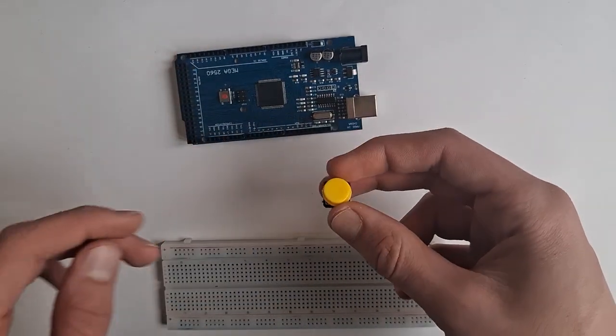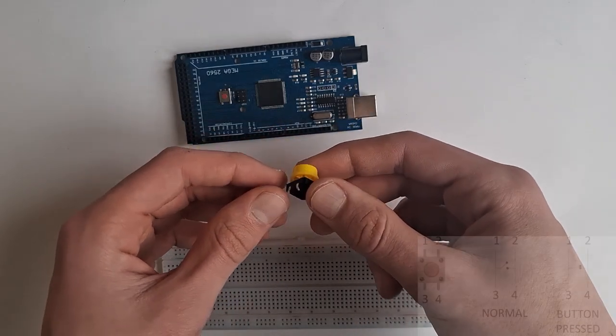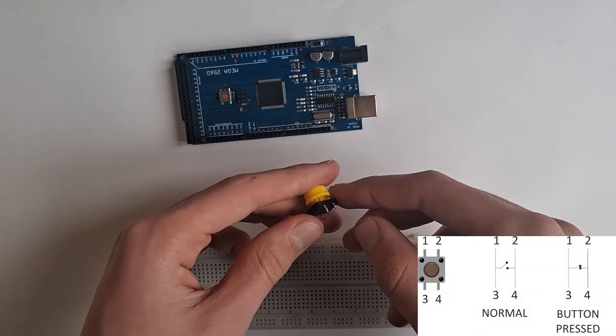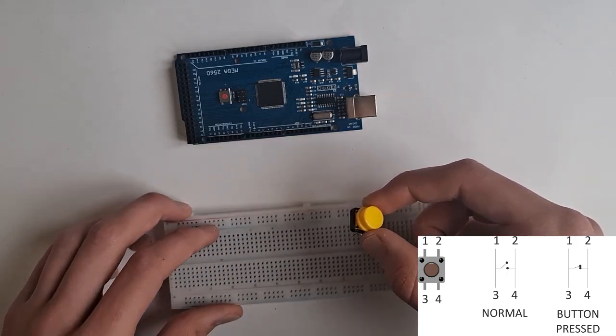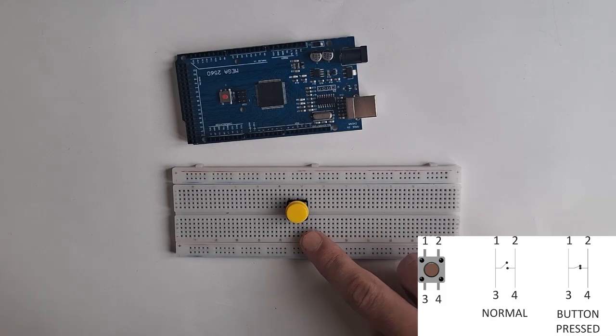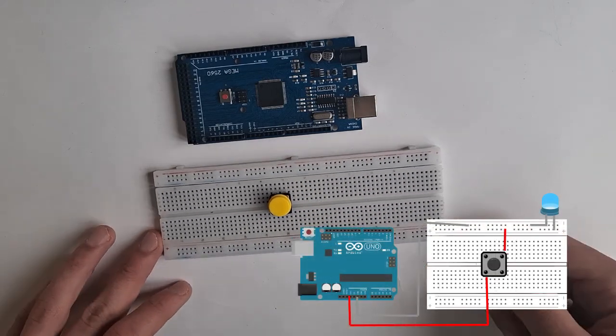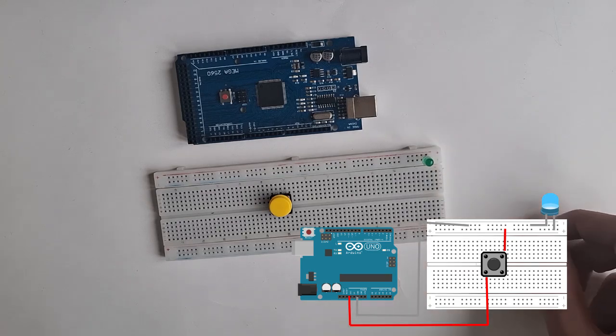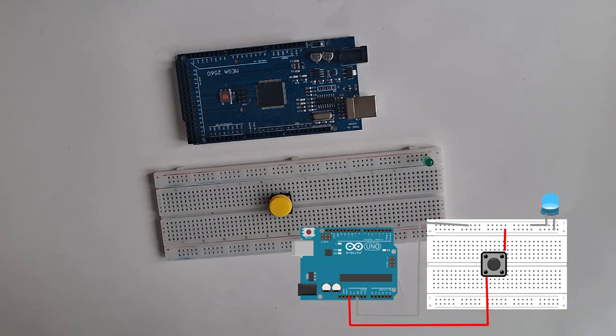The button has 4 pins and is connected to the breadboard, and now you see how the button works. If we connect pins 1 and 2, then the current from 1 goes to 2, or vice versa. We can also connect 1 to 4 and we will get a button, which when we press, the current from 1 goes to 4. In this way, we can assemble a small project that will represent a button and a light, and when we press the button the light will turn on.